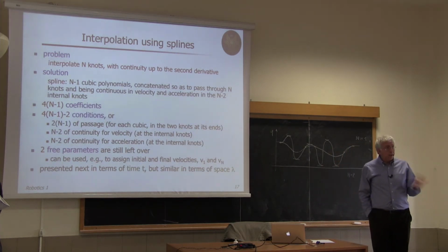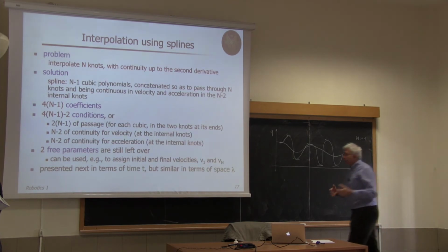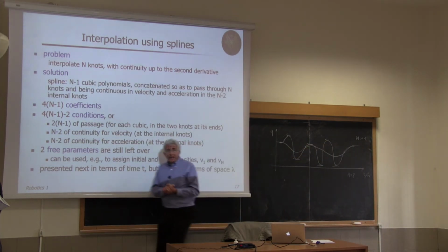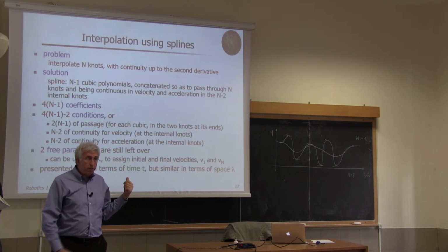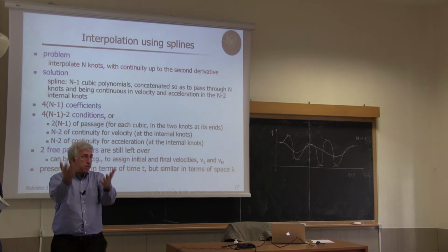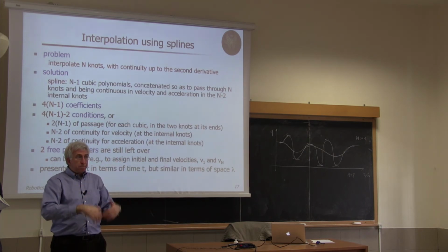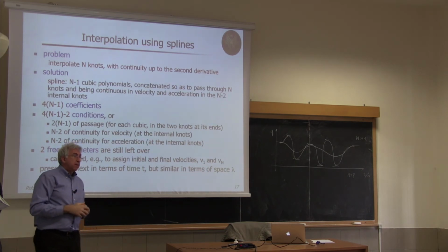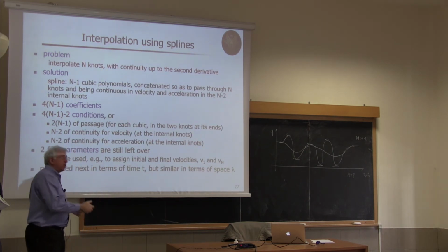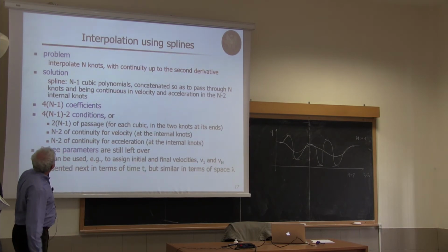But you cannot guarantee to go there if you're using only a single high order polynomial. And this motivates the use of patching things together, exactly like in the 4-3-4 case. Now we are generalizing it to a generic number of nodes, n, that can be even very large. And we have seen why it could be very large, because remember this transformation. You get a few points in the Cartesian space from the task planner. They are interpolated, then oversampled, and then all these points are moved to the joint space, and then you have to do the interpolation. This is exactly the case where those results apply.